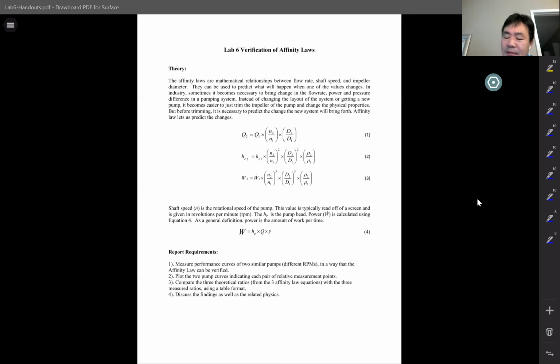When the pump runs longer, the impeller gets damaged on the tip, so it will sometimes perform non-uniformly. So one practice is to trim the impeller, so the impeller becomes smaller. It still works, but after you trim it, it looks better and produces pretty uniform performance.